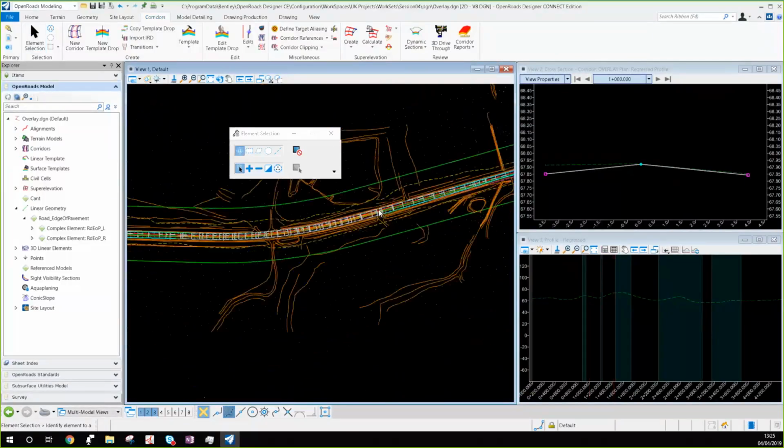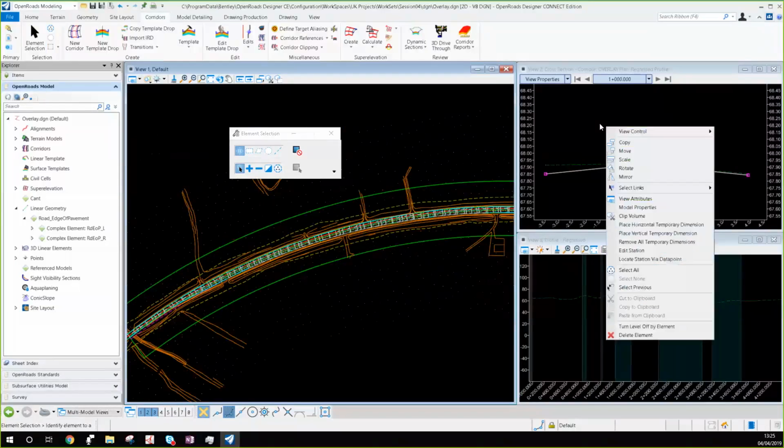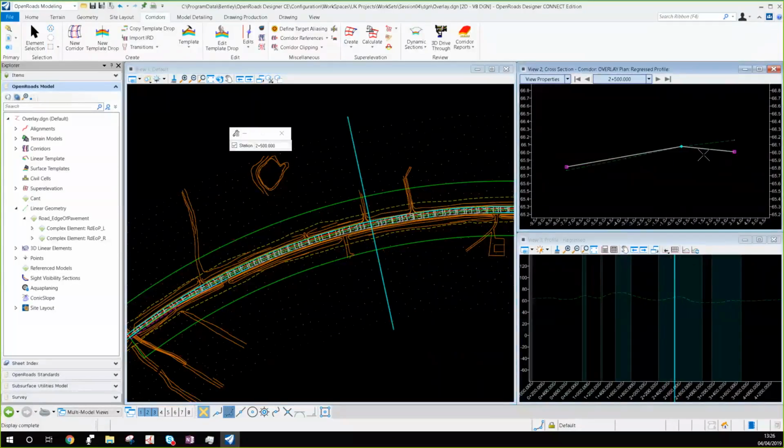In this case, if we go in a curve to have a better look in this view, let's say in the middle of this one, you can see that it didn't work on this side. It's because we forgot to check the super elevation flag on this point.